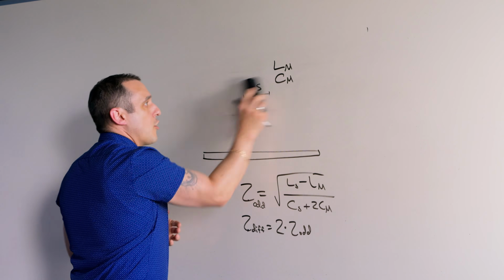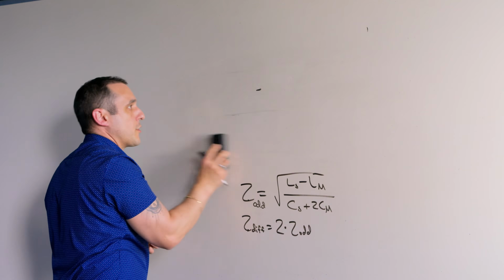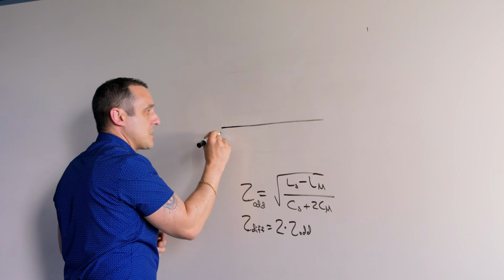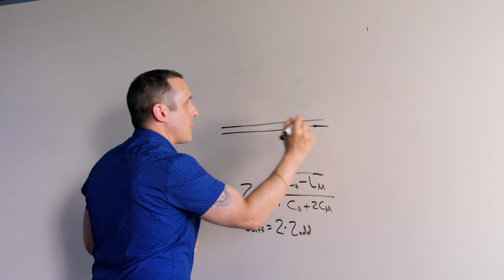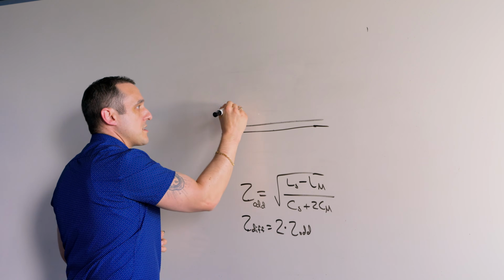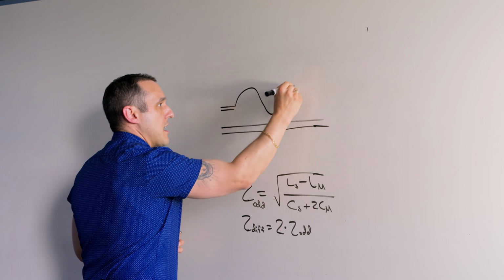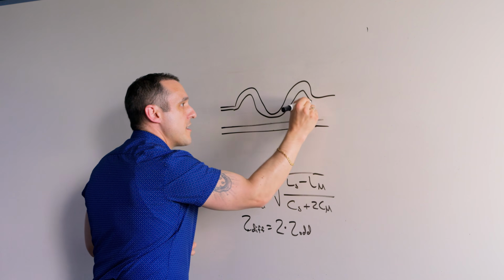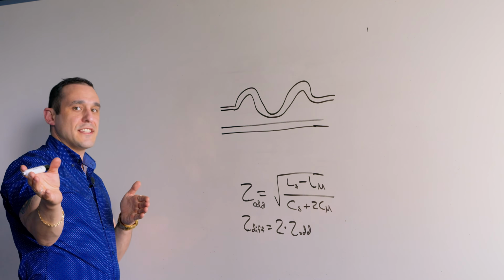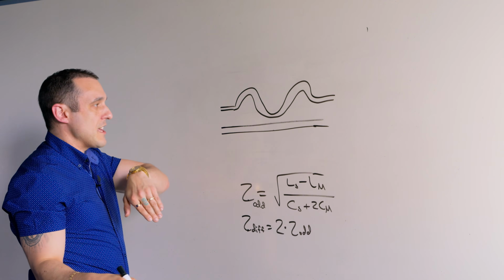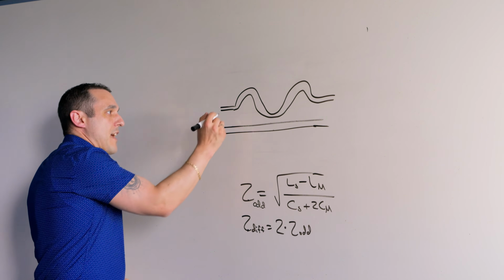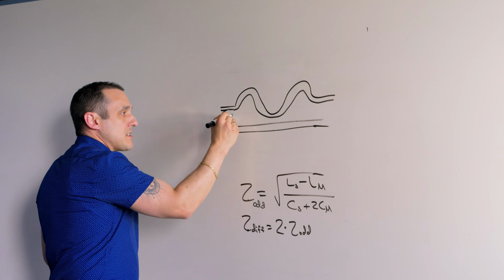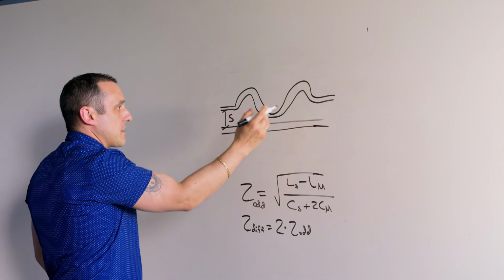So if I just look overhead here at this differential pair, you will see that we have one of our traces and it's mismatched in time from the other trace. And so we would basically add in something like this kind of sinusoidal length tuning section. Obviously, this is not a very good drawing, but you get the idea here. You basically add in this length tuning section, and in the process of adding it in to compensate the time mismatch, this spacing will deviate along the length of this route.